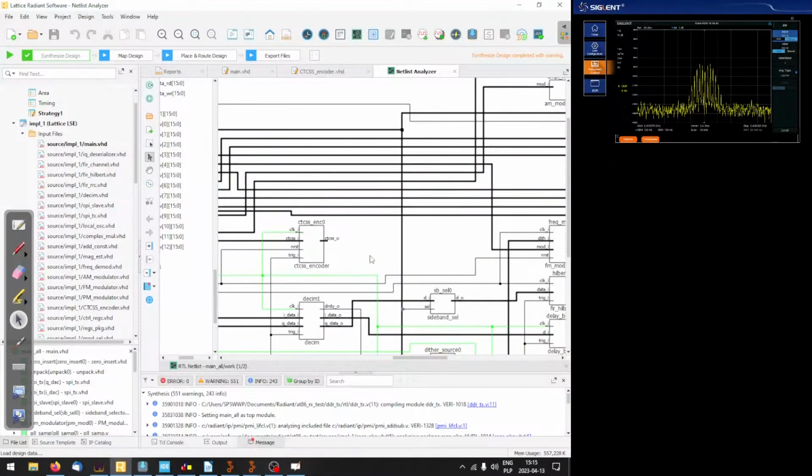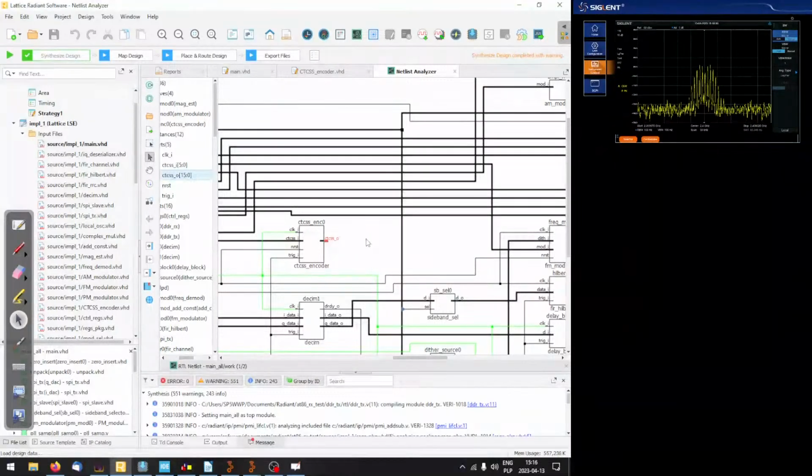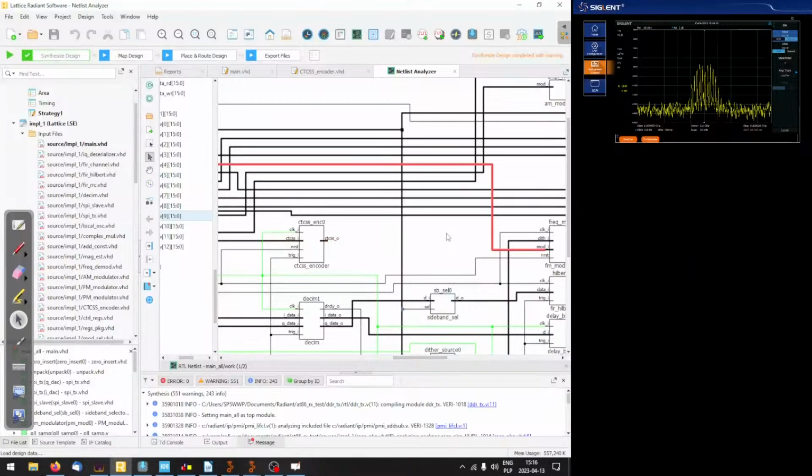All right, so the CTCSS block should be working right now, so all we need is an adder. So let's try and do this. Let's take this signal, which is 16 bits, and that's a signed value. Actually, the output is unsigned, but for the adder, I believe it doesn't matter if the signal is signed or unsigned. So the adder just adds the values together and doesn't care. And add it to this.